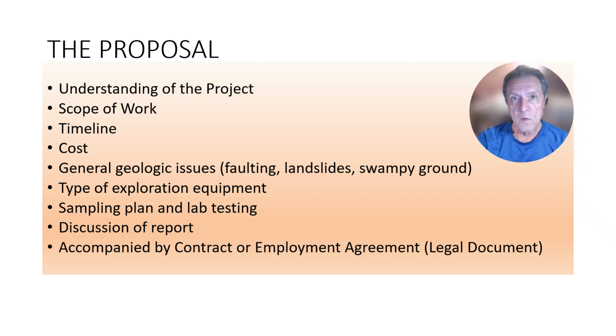You have to know what the scope of your work is going to be, whether it's going to be just 1 or 2 borings or 15 borings or additional exploration work that's going to take a long time and it's going to cost more money. You might also address any need for geologic observations during actual construction or earthwork of the project. That can be critical. So scope of work.